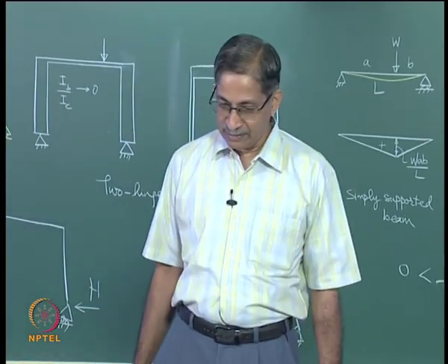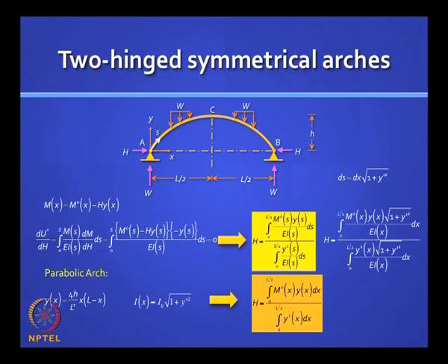It is very easy to do that. Integral y squared dx from 0 to L by 2, this denominator is a constant which you can remember, because y is this, there you are, 4h squared L by 15, okay. That is an easy integration to do. So remember that and you are ready to solve arches.